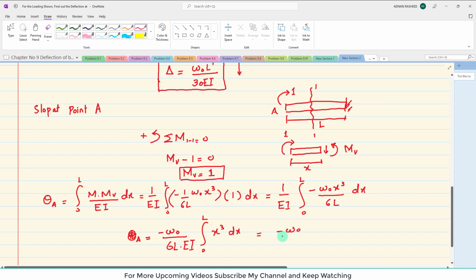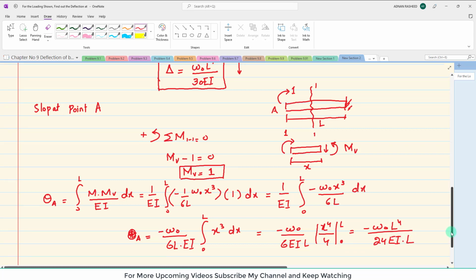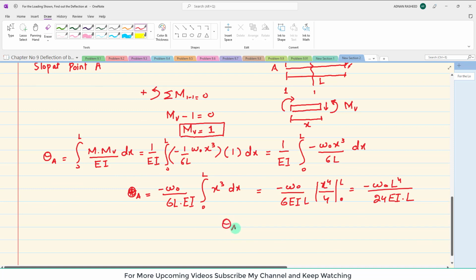So minus W naught over 6EI into L, and this will be x^4 over 4, and the limit will be from 0 to L. When you put the limit, it will be W naught L^4 over 24 EI into L. So the slope at point A will be equal to minus W naught into L cube over 24 EI.